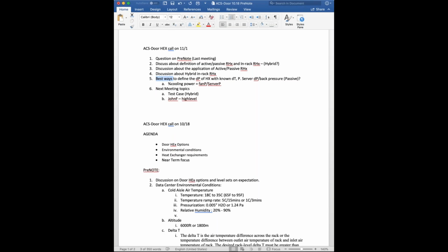I can put in an email what the normal commercial coil will do. That's no problem. But again, is it relevant if we're looking at our conversation 10 minutes ago, where we walk on a road where it should be a hybrid solution, it makes sense. The amount of air through the coil will dramatically be less if it's only for 20 or 30%. And if the air is down significantly, the pressure drop will also go down a lot.